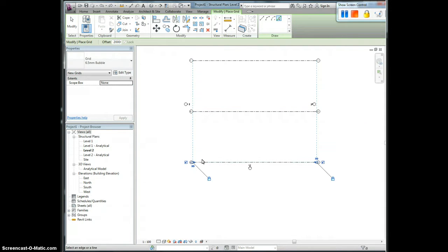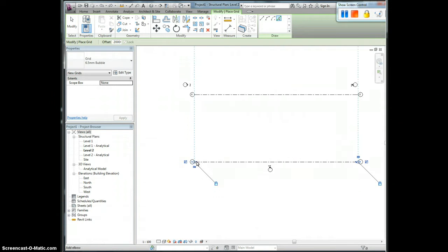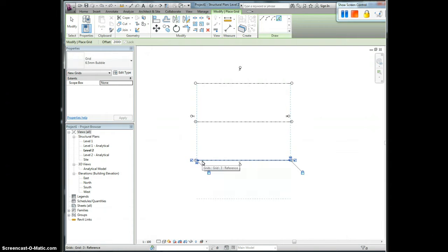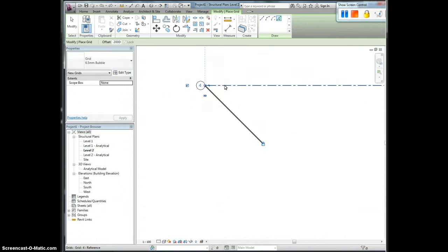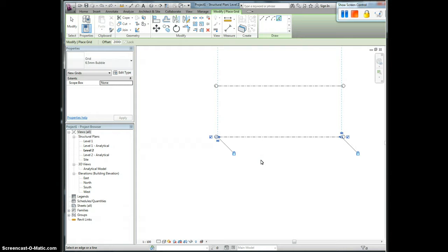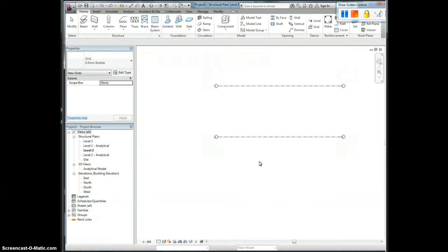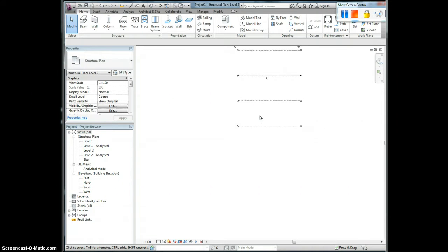And you click. This is now 3 here. Okay, so that is correct. Only when you see this dash line indicated there, then you click. If you don't see that, don't click to confirm. So this is number 4. Now I'm going to draw line number 5. I only need 5, so I finish this one. Now I press the escape key twice to finish it. With this, I have drawn all 5 grid lines.